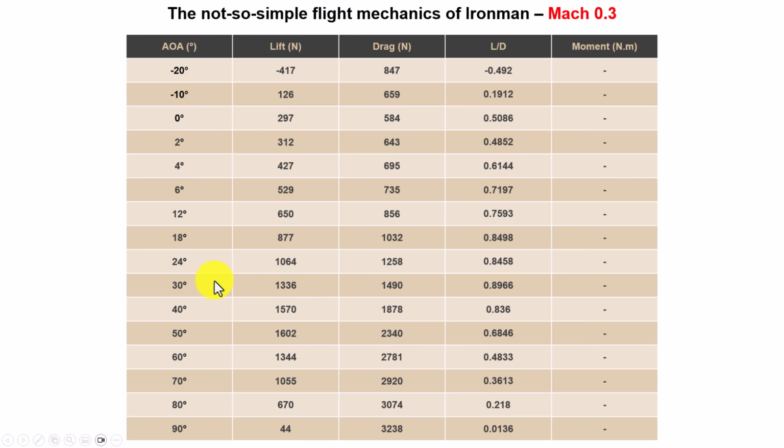But this comes with a penalty, that is drag, and drag is very, very big in this case. So Ironman is not aerodynamic at all. We can measure that efficiency by looking at the lift to drag ratio. For those that do aerodynamics, a good lift to drag ratio of an airplane, general aviation or commercial airliner, will be something about 8. And see that here we have less than 1. So basically you are generating more drag than lift. It's not aerodynamic at all.